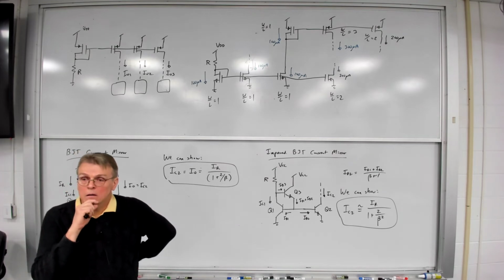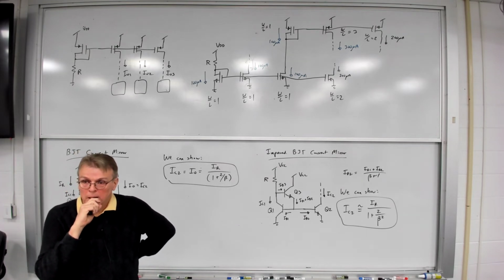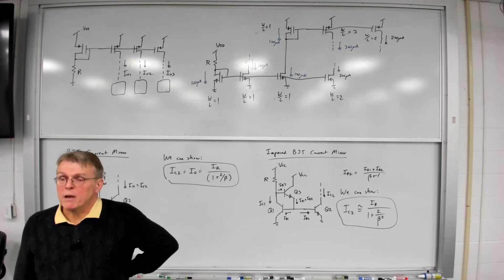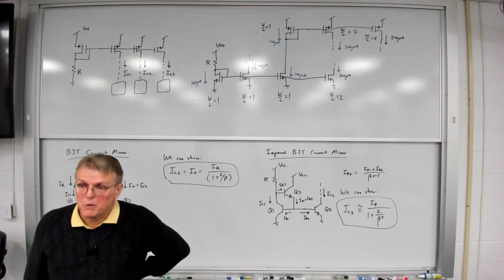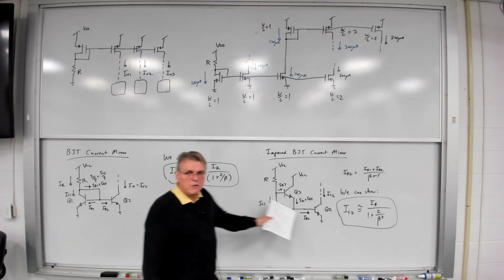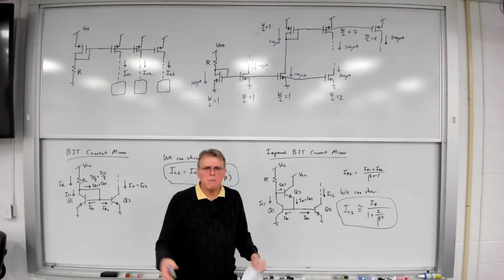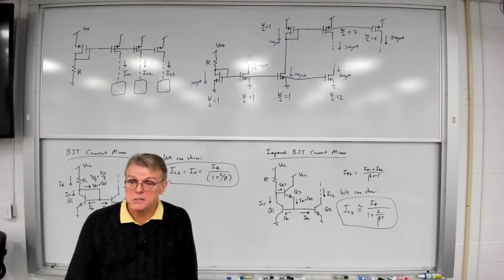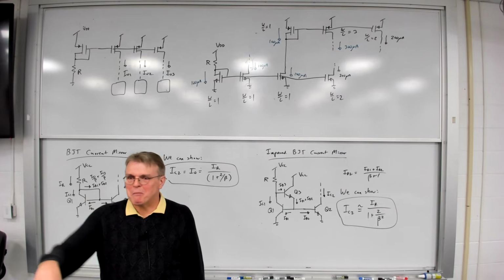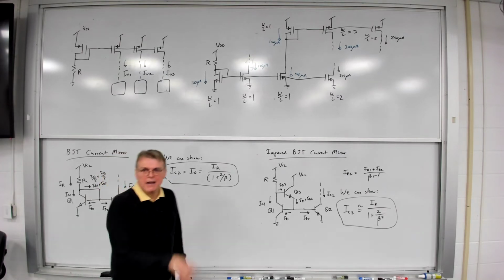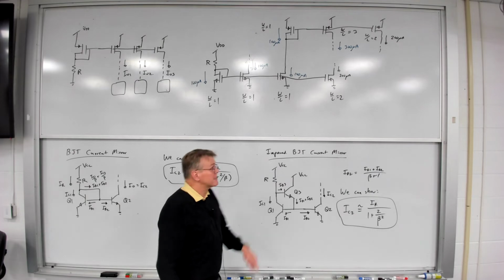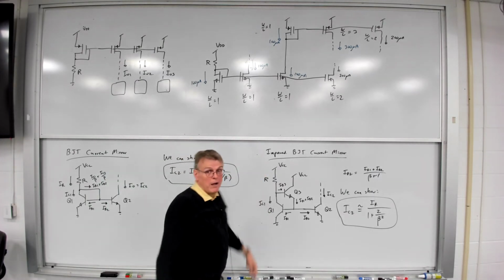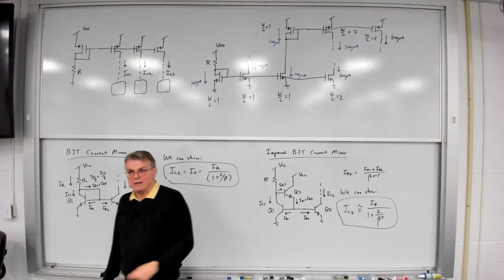Yes? So do you need like 3 transistors to make that one compared to like 2 transistors for the MOSFET one? And why would you want to use this one over the MOSFET one? Well, it depends upon the devices you have available to you. Do you have, for example, a bipolar process you need to design this in? In other words, you're right. If I were going to do this between a BJT versus a MOSFET, I would just use the MOSFETs. But I'm showing you this because in some cases you may be dealing with an older bipolar process, which has PNPs and NPNs but no MOSFETs in it. So in this case you want to understand how this technique works. But your point's well taken. The MOSFET technique is infinitely more common in modern design. But just for completeness, I wanted to show you guys this as well.